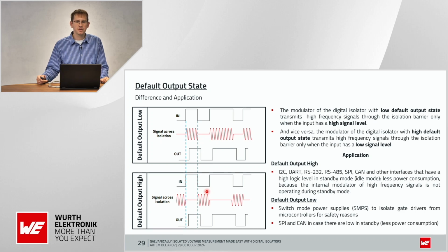And speaking about digital isolators with default output low, it makes sense to use them in switch mode power supplies to isolate gate drivers from microcontrollers for safety reasons, and also it makes sense to use them in SPI and CAN interfaces in case they are low in standby. Again, because of power consumption.